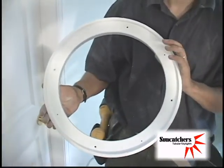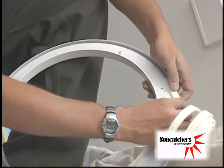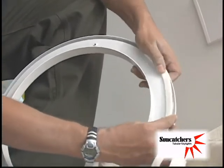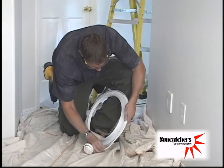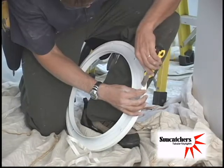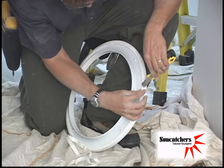The white ring is sealed to the drywall by applying a foam tape on the top side. This will prevent warm air from escaping into the attic. Remove excess material with a utility knife.